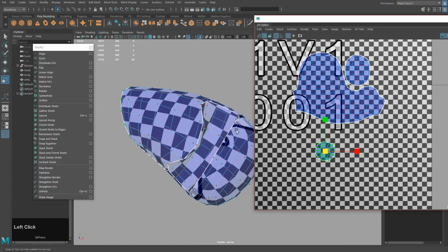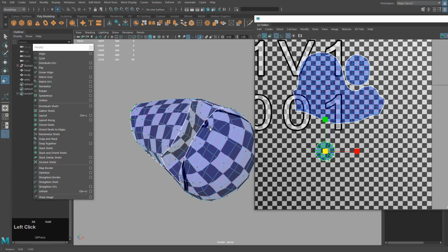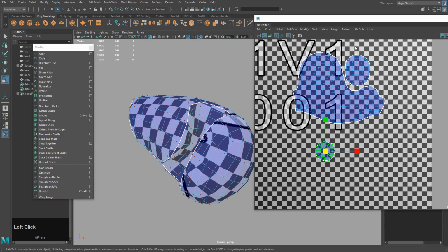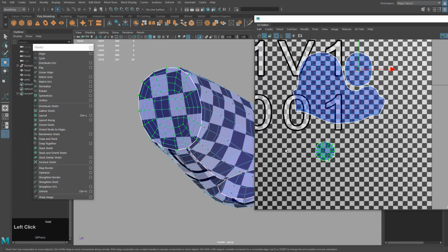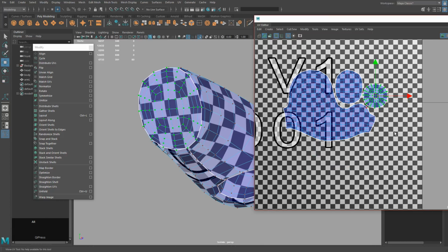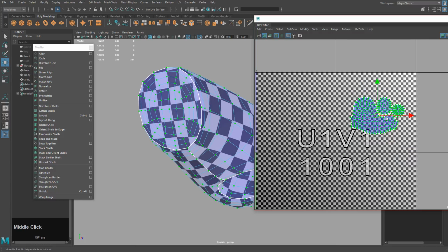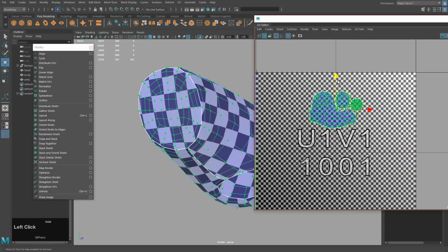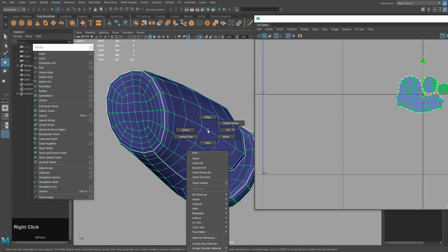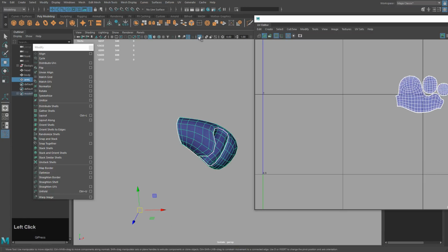If I click the checkerboard, I can see if everything's lining up. So the inside and the outside look pretty much the same. We may want to just scale this up a little bit. And this one, definitely need to adjust the scale here, like that. Even though we don't see it, I'm still going to line this up and just place that there. And snap it here. I'm going to snap it here actually to this grid. Turn the grid off, the checker box off. Okay, now bring back the rest.